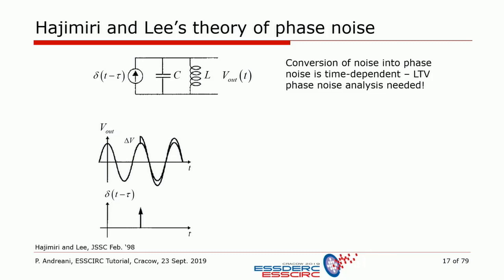So for instance, if you inject it in this case, basically at the top of an oscillation, you see that you do not really change the phase of the oscillation at all. The phase is still the same. So in this case, there's basically no phase noise. Okay, it is a simplification, of course, but nevertheless.